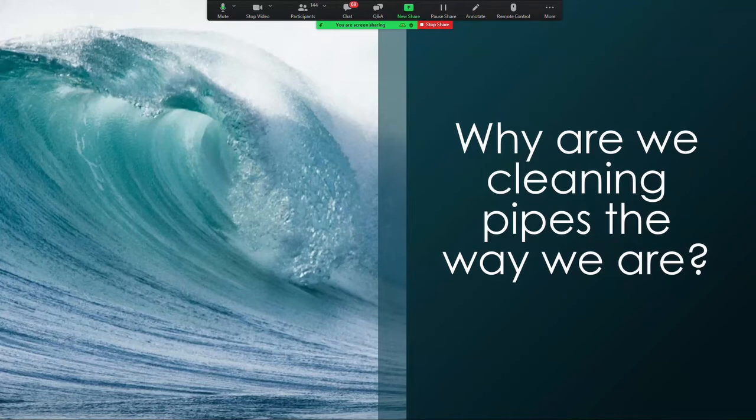Yeah, but at a high level, municipalities every 3 or 4 years. Yeah. Except for notably source control areas. Yeah, where there's a problem, then they go in and do from that. And that's one of the arguments of doing a better job cleaning: if I can get in those problem areas and make sure I get all of the debris and grease and everything else out, then I can probably extend that interval. Yeah, a clean pipe takes a lot longer to get dirty again than a half-cleaned pipe.